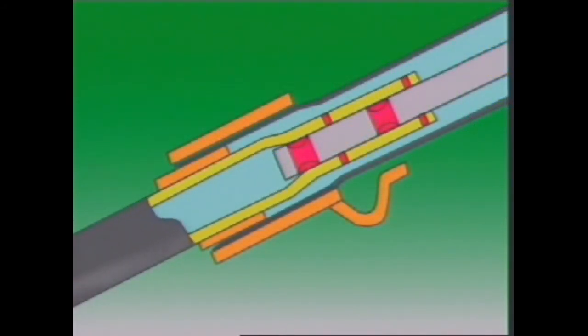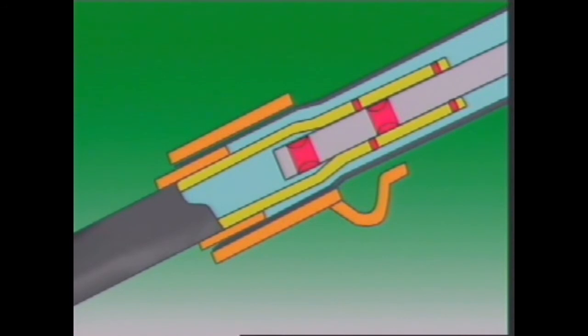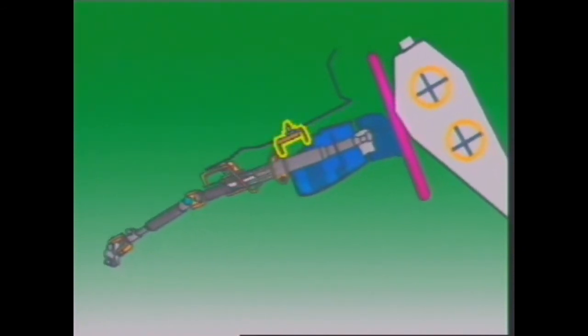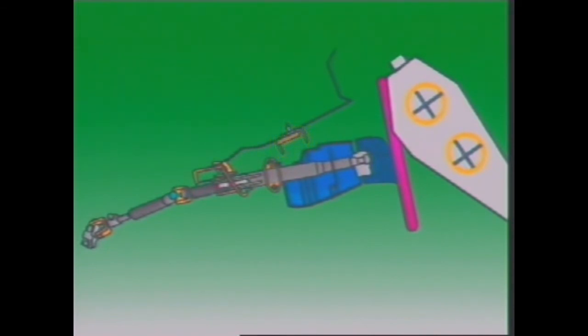Plastic shear pins allow the lower shaft to move over the upper shaft. The second force is the mass of the driver striking the steering wheel. This force breaks the brackets on the upper part of the column, driving the upper column into the lower column. The steering column is connected to the input shaft of the steering gear by a flexible joint. This allows for alignment and reduces the transmission of road shocks back to the driver.